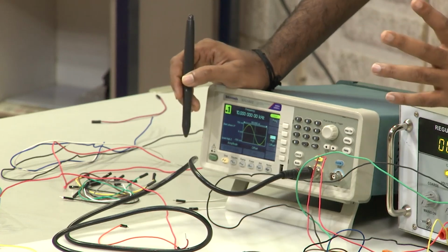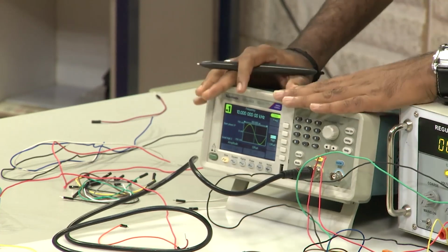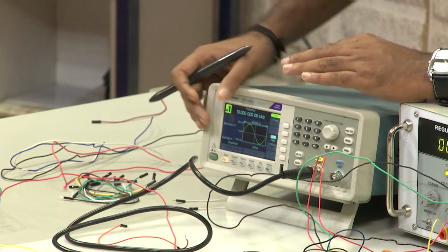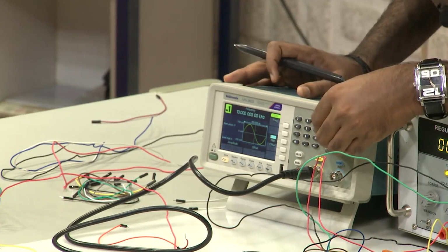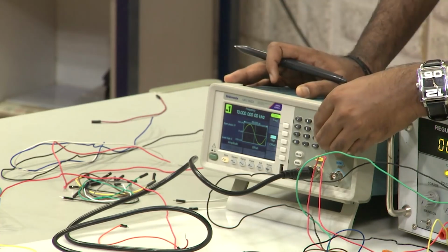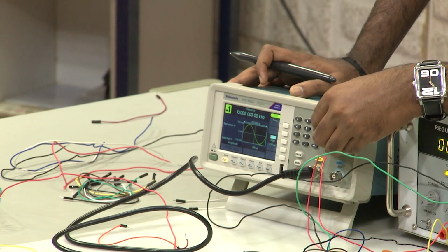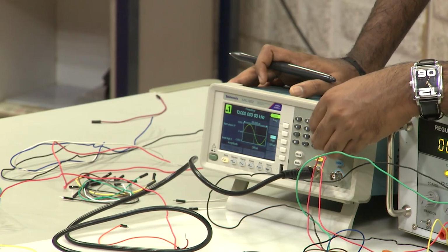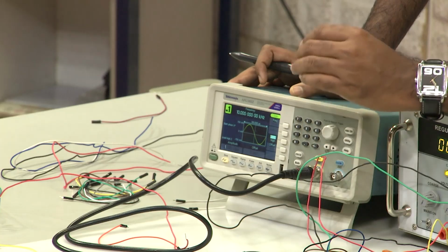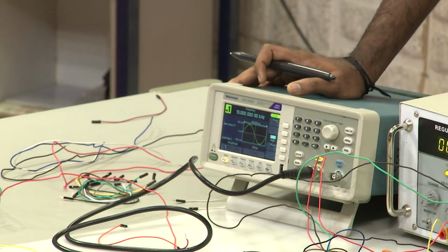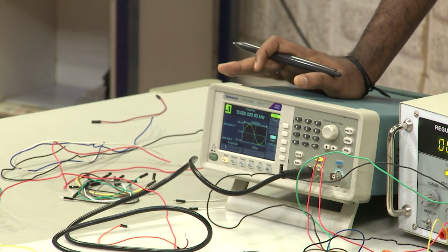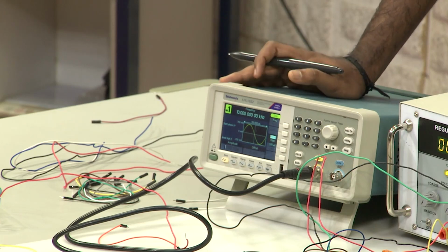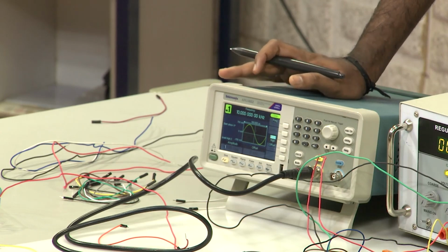Now, next, we will not look at the function generator again. In the function generator, by changing the input with this knob, we can increase the voltage. So, this way I will be increasing the input voltage from 1.5 volt to 2.5, 3.5, 4.5, 5.5 etc., and we will see at what voltage clipping action takes place in the output. By clipping action, I mean the output is getting saturated. So, we will constantly change the input and see how the output is changing.